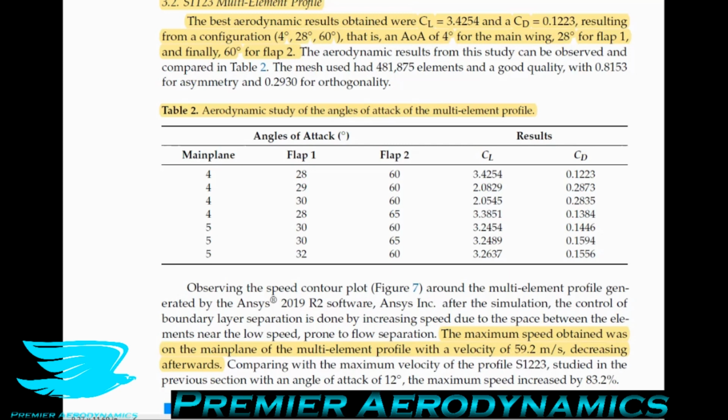Now, something that should be mentioned is that this could also be an artifact of the CFD not being accurate in this zone. However, I think that it probably will be accurate to some extent, like maybe not these changes would be so dramatic, but it would be significant around this angle of attack. So it shows just how fiddly this system is to slight changes in the flow. So this second element can dramatically change the lift coefficient with only a small change in upstream conditions. So what does this mean in real life?